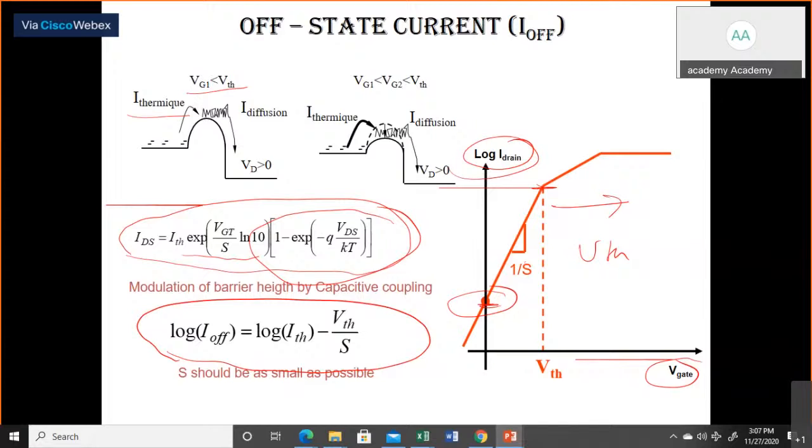If we are designing a MOSFET that will give a lower value of sub-threshold swing, the ideal value of sub-threshold swing, we know that is approximately 60 millivolts. Okay, that came from this particular equation. If you use this equation, we will get this, because ID depends on this particular equation. We get sub-threshold swing equal to 60 millivolts per decade.